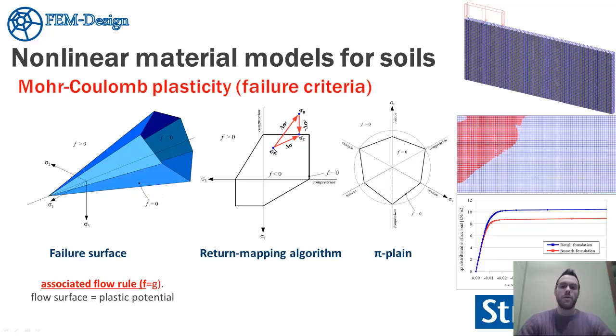So we solve it in different load steps. For example, in the former load step we have the sigma A value in point A. Then in the next load step we have a delta sigma with a linear predictor. Then we have a state at point B, sigma B, but this point is outside of the cone, so it's an impossible state. Therefore we need to apply a returning map to the failure surface.